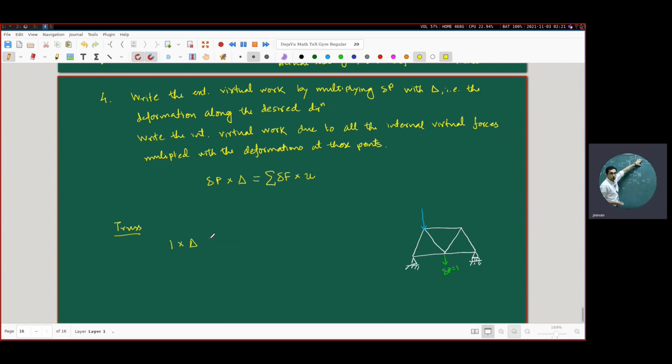And on the right hand side, we have to write this thing. Now, this seems rather impossible to do, but it's not so bad actually, because you can clean it up a little bit by noting that all of these are two force members, and these two force members are basically axially loaded, and you already know how to determine the deflection for axially loaded members. That is something which you have learned in your first year.